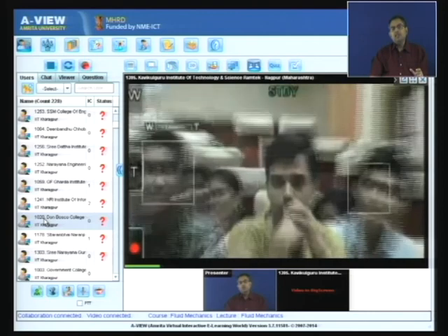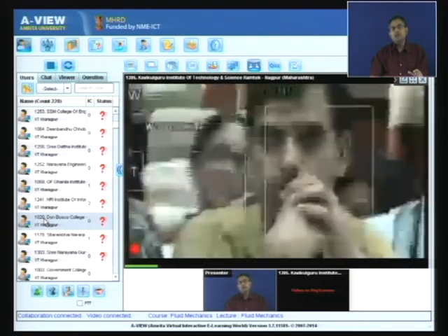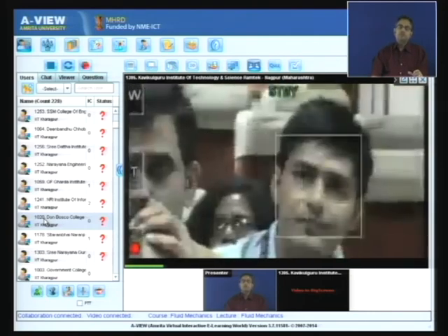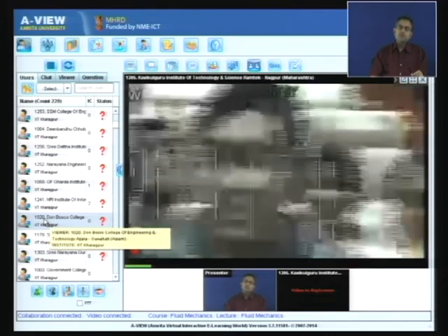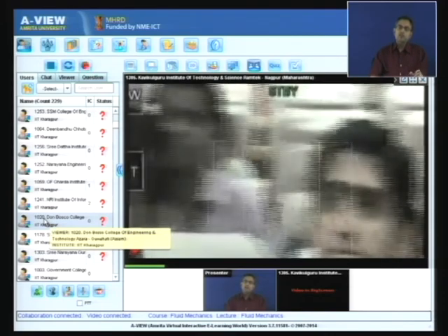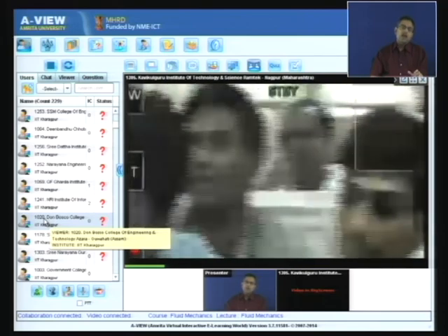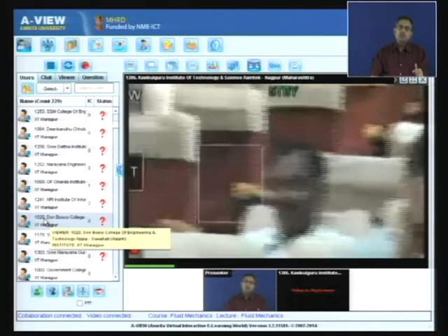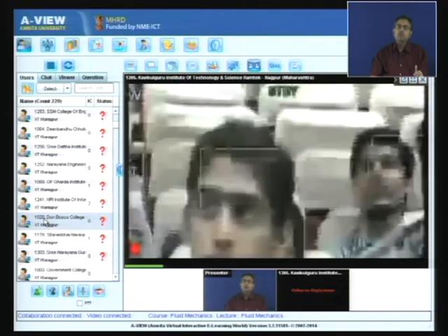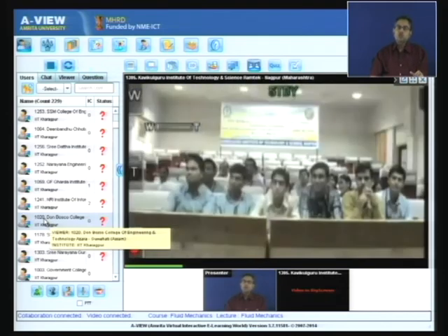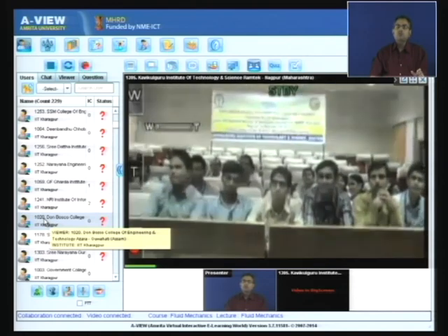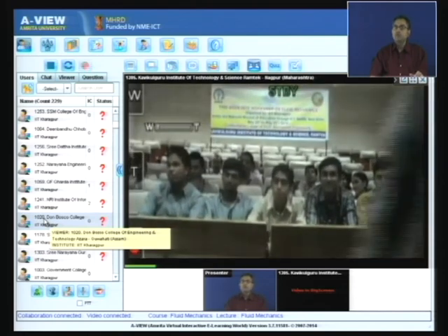So you can divide the flow region into two parts. One part is close to the wall where the viscous effects are felt, and you have to write the equations with viscous terms. Outside that region there is no need to solve the full equations with the viscous terms. You can neglect the viscous terms and solve the dynamics of inviscid flows.